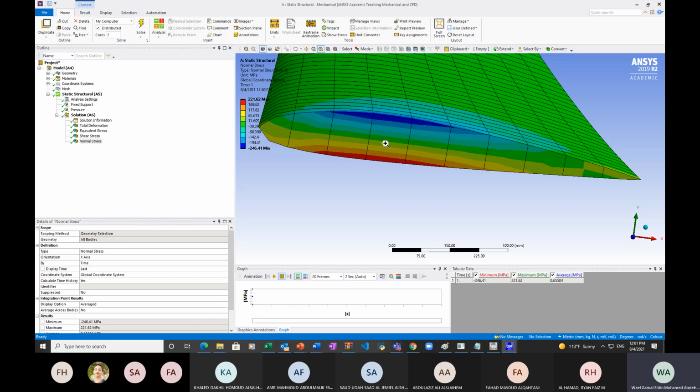And you can see the gradual variation between the compression and the tension, which is the bending stress distribution we are accustomed to, the sigma, right? Sigma is linear, changing from maximum positive to maximum negative, and it's 0 in the middle. 0 here is the green one, right? The boundary here is the 0. So you can see this is like the neutral line of the wing.